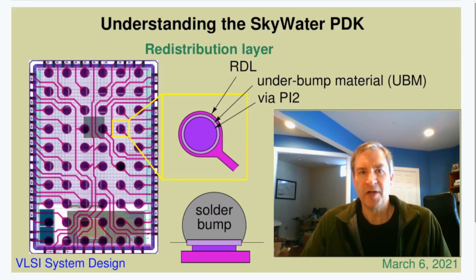And these things are notoriously tricky to solder when the packages are huge, like they are for modern microprocessors and graphics processing chips. But on a fairly small scale, they are not too difficult to work with, and the solder bump size and spacing can be made compatible with low-cost circuit boards. The eFabless Caravel harness chip was designed with this in mind, with a 6x10 array of solder bumps that is compatible with a cheap 2-layer board.